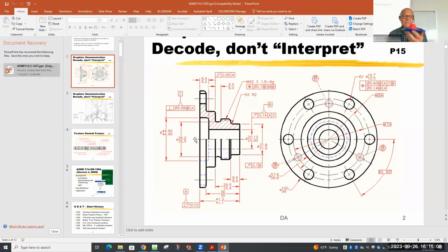In fact, if you put something down that doesn't rock, it's sitting on the 3 highest points of whatever you put it on. They're so small you couldn't see them. It's not like you're looking and seeing little bumps, but there's always surface irregularities. And what does it do? The 3 highest points of contact are the ones that control it.